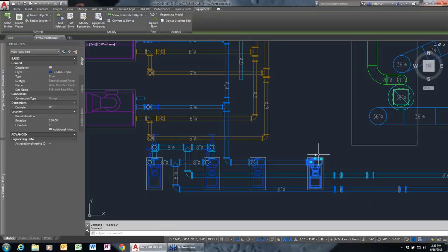The difference between a pipe and a plumbing line in AutoCAD MEP is that a pipe actually will be modeled in 3D with 3D geometry and 3D space. The plumbing line is really more of a schematic representation. So often when people are doing plumbing layouts, especially in the past, though today people are actually starting to model pipe plumbing, you can just use a schematic plumbing line instead.